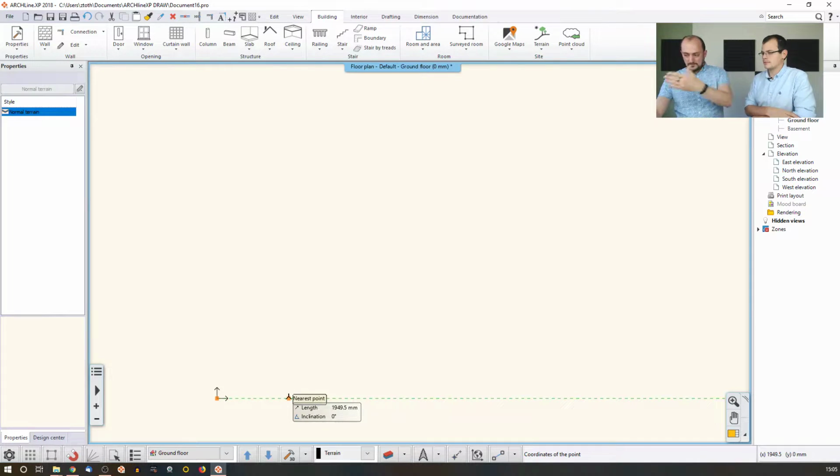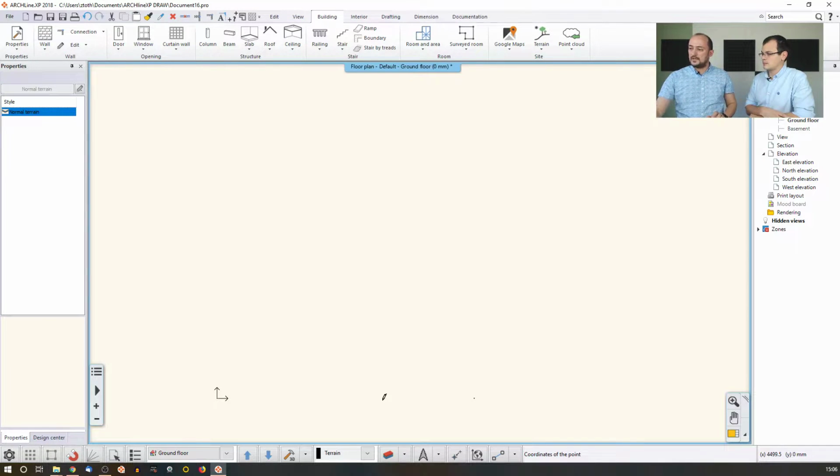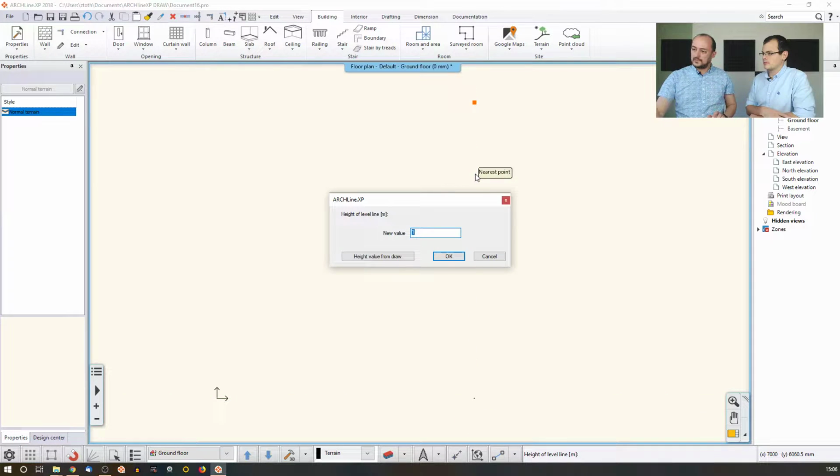Yeah, and now I'm just telling the software I'm going to the right, and I just type, for example, 7,000. Now I'm working in millimeters, so 7,000, that's 7 meters. And then again, I type that, okay, this should go again to 1 meter. And then from here, if I would like to go up, I just click here. And then now let's just move the mouse above and say, okay, this is 8,000, for example. And this is at, for example, let it be at 2 meters.